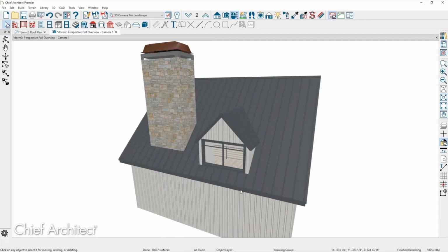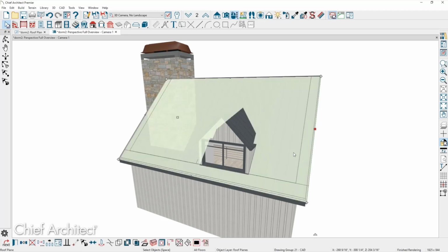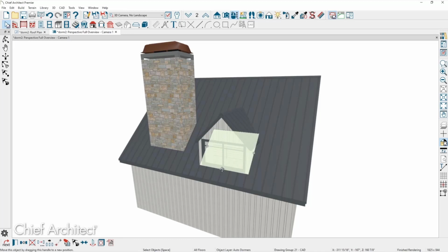Exactly. So that exterior face where the window is, which is a gable dormer, is in the same plane as the floor below it. Right. So basically what I would probably do is modify this roof back in here and pull it so that I can peel that back right down into the front in that area.